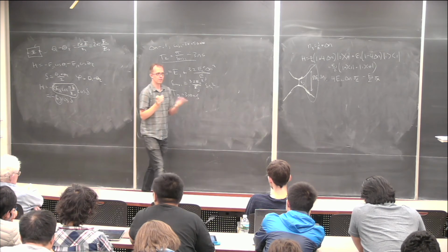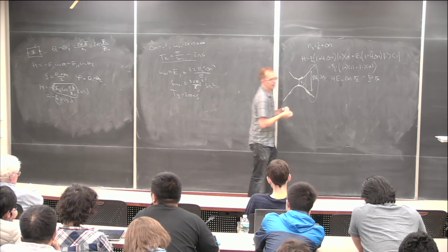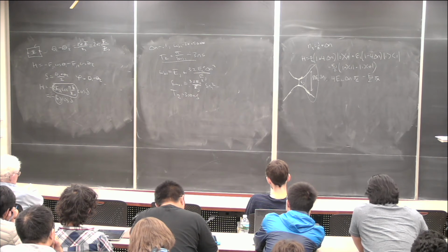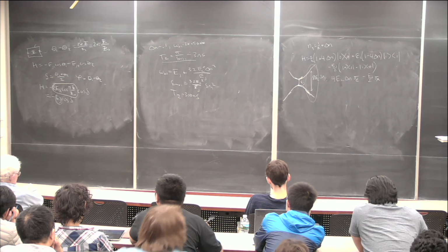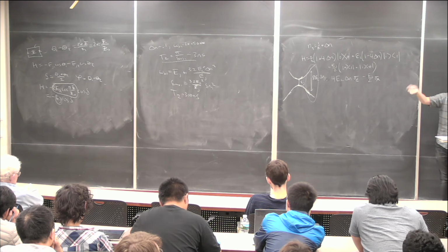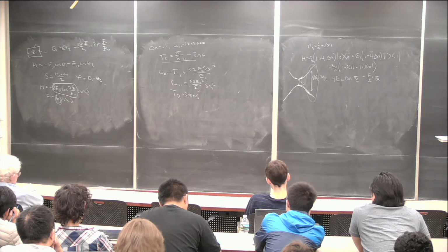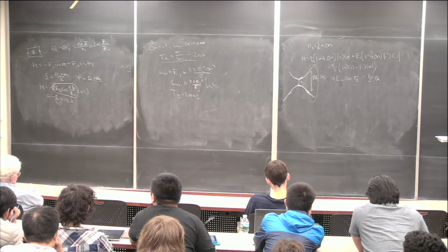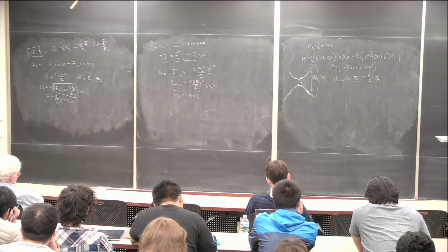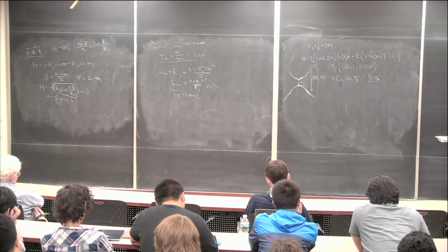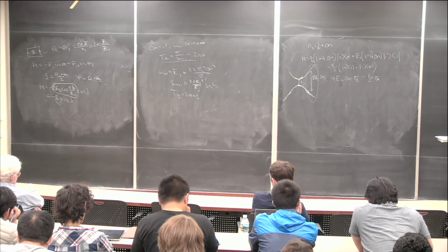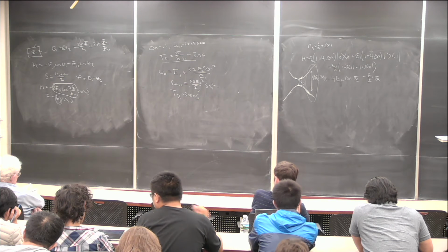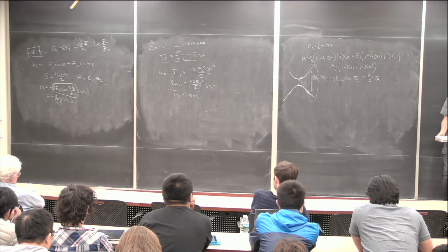But if we introduce a new knob, then we introduce a new source of noise. And so now you have to think about whether noise in the magnetic flux is going to actually wind up causing dephasing as well. And you can do that exactly the same way by defining the derivative with respect to flux and figuring out what the T2 from that is. It turns out that empirically, the flux noise that we see when we make these devices is much smaller than the level of charge noise we see. So it's typically sort of 10 to the minus 6 flux quantum or so, and not 10 to the minus 3 electrons.